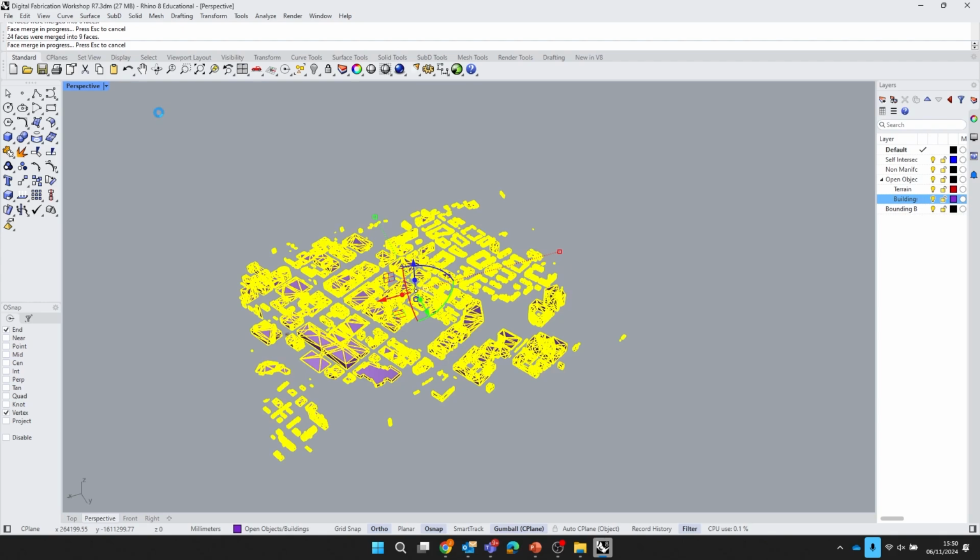So that's going to do some thinking for a sec. So you're not a big fan of view capture to file? No, I quite like view capture to file, but if you're doing it the right way. If I'm doing like a render or like a shadow study, I'll do view capture to file to capture that. But then I'd also do make 2D to get the vectors, lay it on top, and bang, there's two. Get such a better result. But yeah, view capture to file is great. So much better than a screenshot at least. Still see people submitting screenshots.